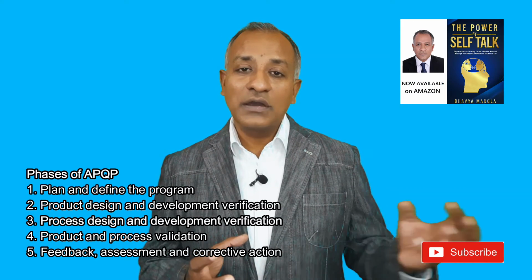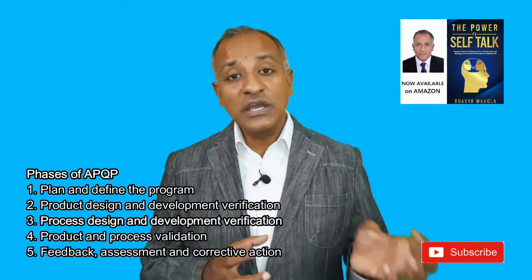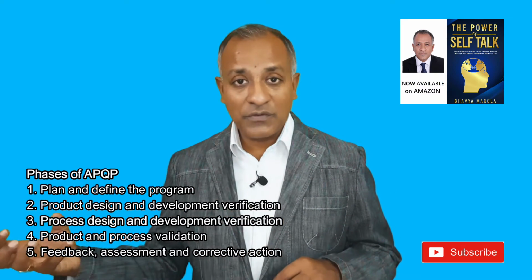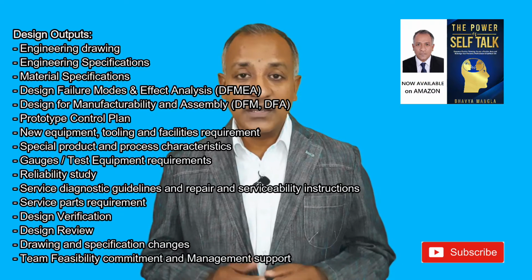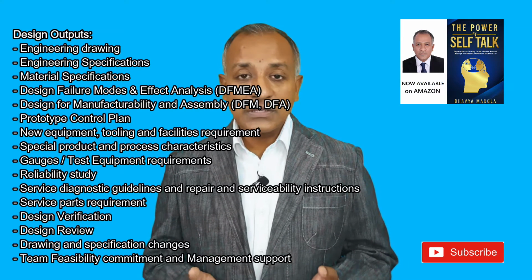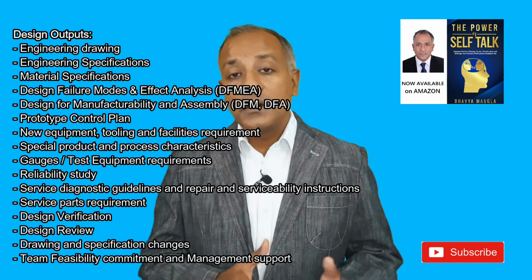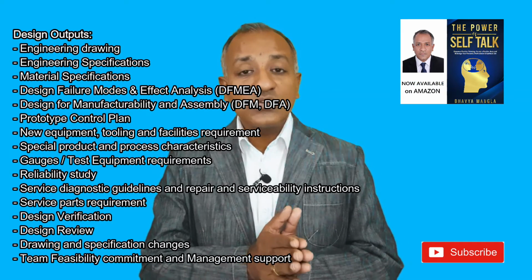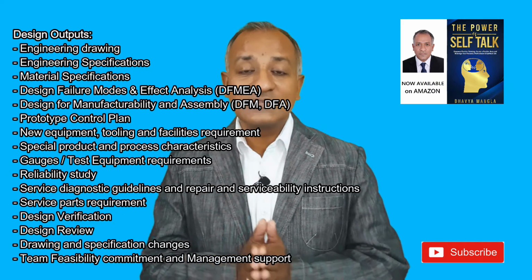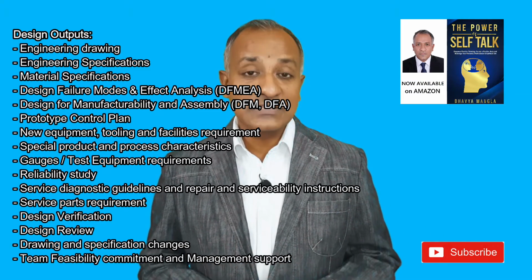So it's very important that whatever inputs that an organization or the process owners are receiving from the previous phase, they must incorporate them effectively so that whatever output is coming from this phase fulfills the customer requirement. If I talk about some of the key inputs which are coming from the product design phase, that includes engineering drawing, engineering specification, material specification, then control plans which may be related to prototype control plan, DFMEA, identification of special characteristics, reliability studies, identification of design for manufacturability and assembly, and many other things. All these things become key input for the process design phase.